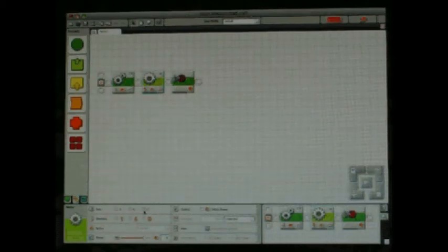Again, you can only set one motor here, so you have your port you can pick, but you can't pick multiple ones. Again, you have your direction. And you have your action, which, if I go over here to duration and change it to something other than unlimited, because action is ignored when duration is set to unlimited, you can set it to constant, ramp up, or ramp down.